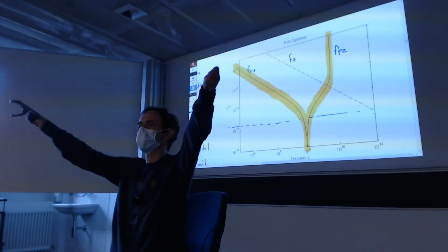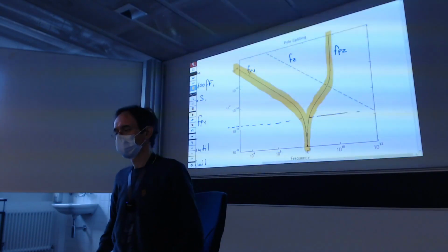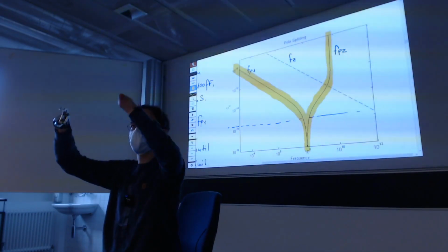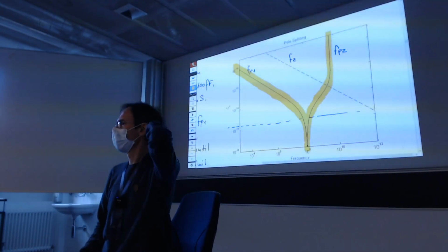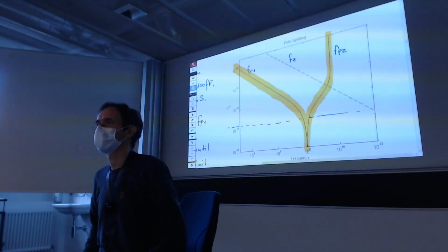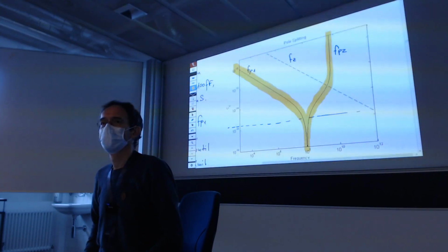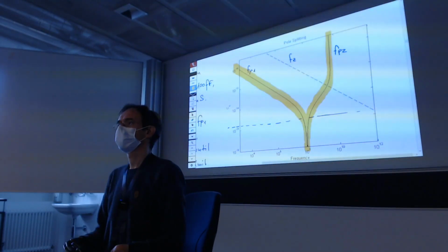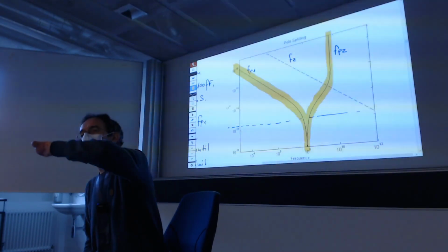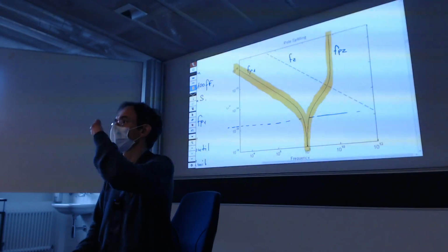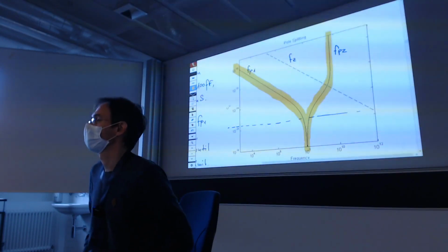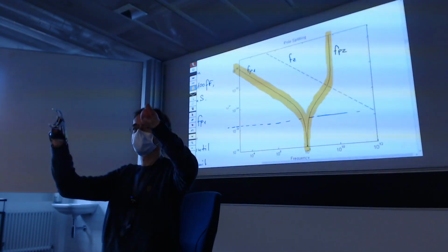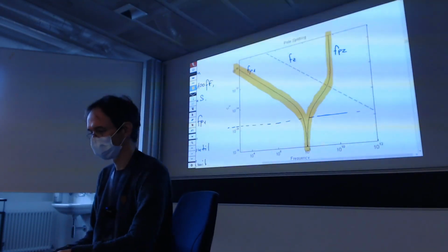If the two poles are very much apart, then you can make it stable, because the first pole will cause a roll-off in the frequency, and when the second pole comes, you are already beyond unity gain or something like that. So pole splitting, which this is called, you can achieve by having a capacitance between the output and the input. There is one there anyway, so it's this CDS1. But if you increase that, then you just split the poles apart further.